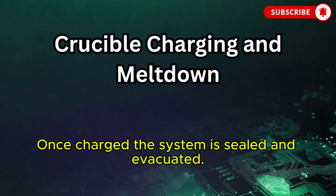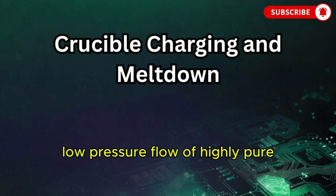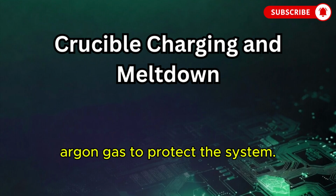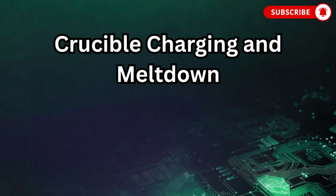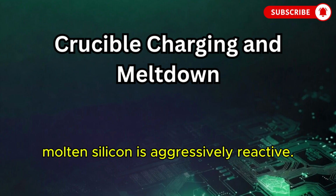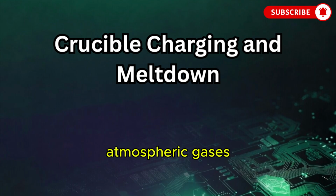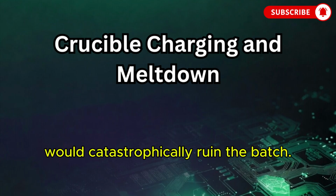Once charged, the system is sealed and evacuated. We introduce a continuous, low-pressure flow of highly pure argon gas to protect the system. At 1500 degrees Celsius, molten silicon is aggressively reactive. It will readily oxidize or react with nitrogen, meaning any ambient atmospheric gases would catastrophically ruin the batch.